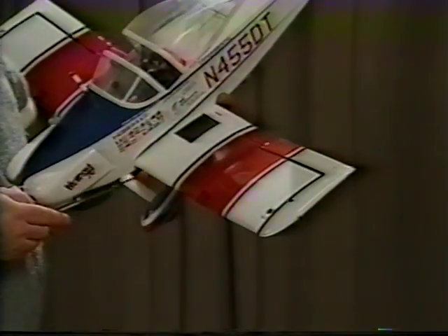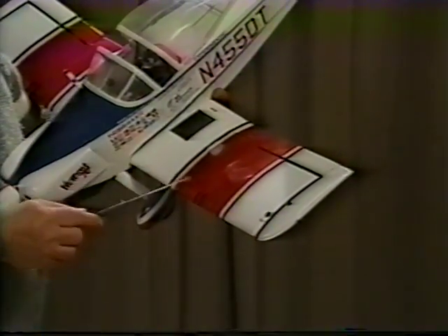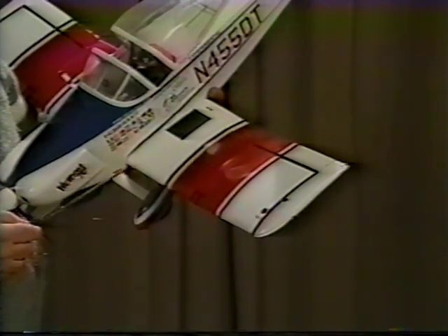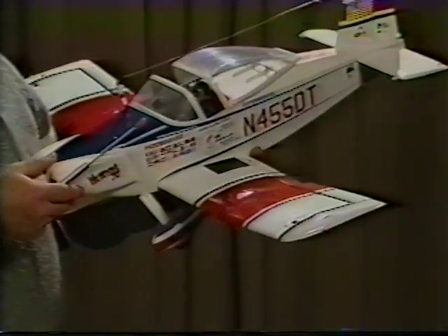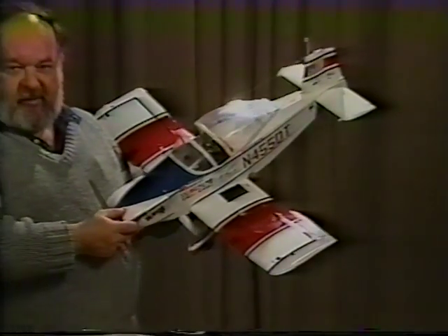It isn't ideal from the standpoint of the stall pattern. You maybe would like it a little bit further inboard, but it's really not too bad either, because there still is a generous portion of the outboard wing that will be working. This sort of represents a normal design compromise.